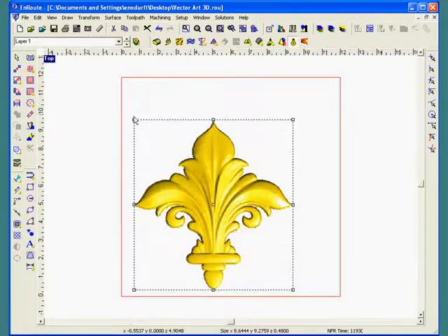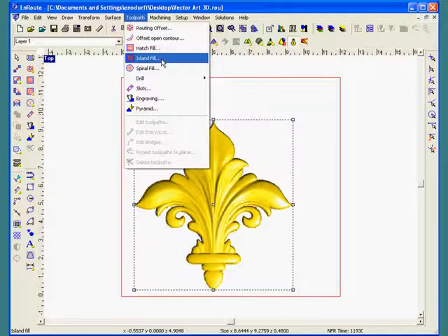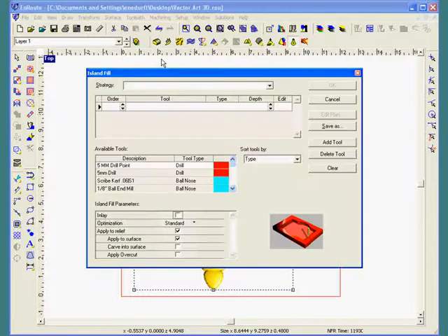Now we're going to create the rough toolpath, and to do this we're going to choose between an island fill or a rough fill, and the hatch fill will go back and forth. An island fill will do a contour of the part and maybe be a little bit more efficient. So I'm going to choose island fill. Because I have a relief selected, it automatically prompts me to apply this to the relief. And in EnRoute, the toolpath engine is the same for the 3D and 2D objects.